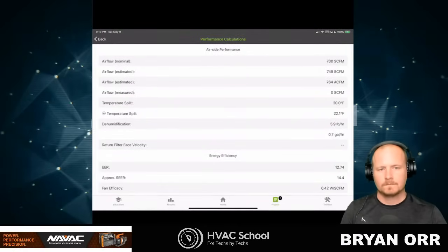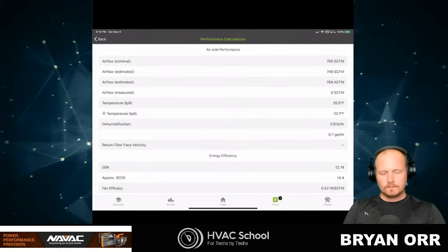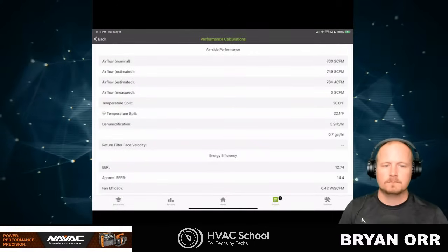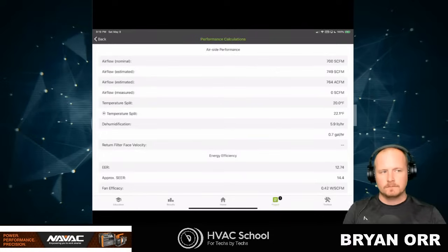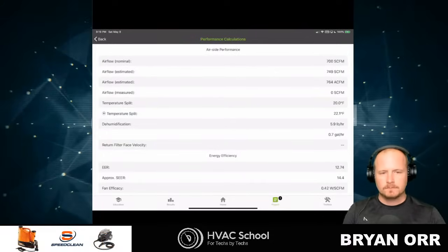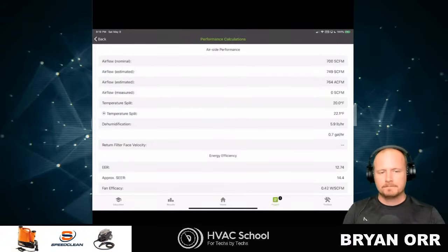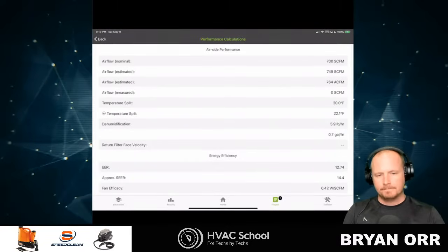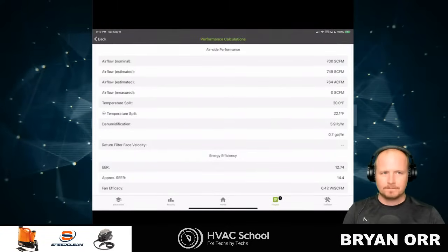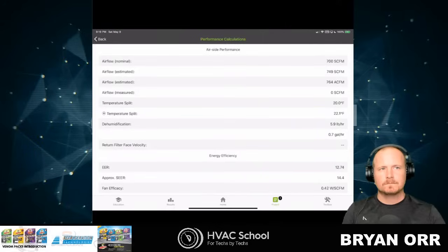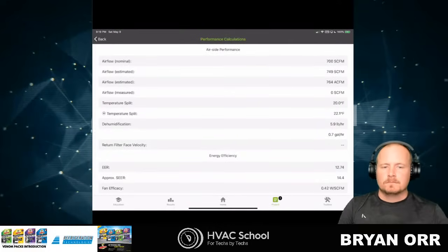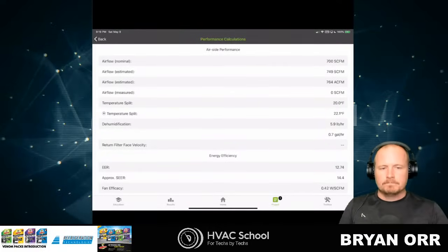When we're talking about all this COVID stuff, we're talking about how important filtering the air is. A lot of filters are running way over 300 feet per minute of face velocity, which is where they should be. They're running up in the 700 plus range. So most of you out there are going to find out you need about twice the number of filters that you have on the system. It's going to be very, very common.